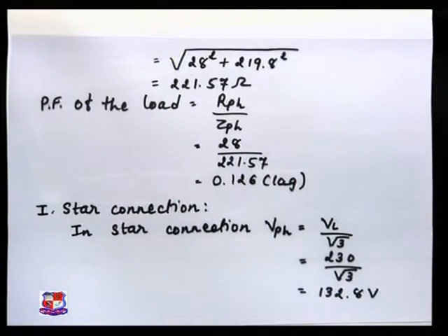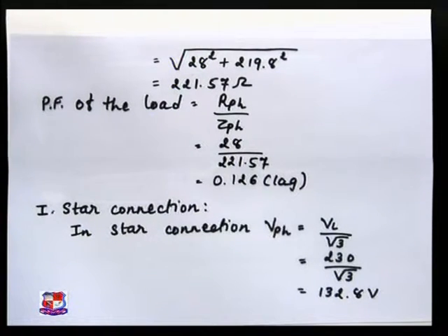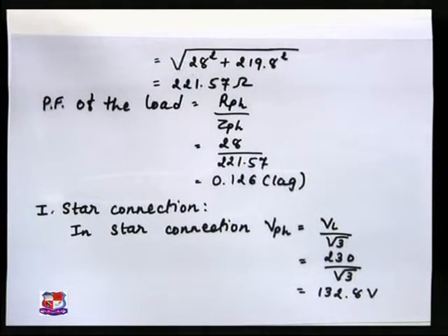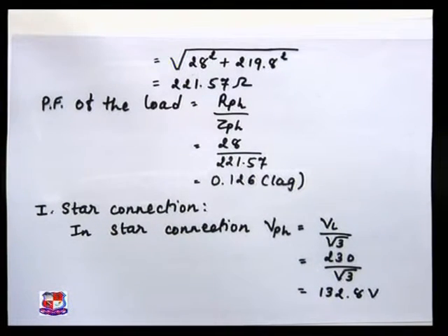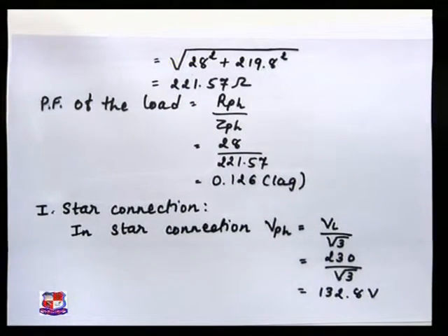Now the power factor of the load is R phase divided by Z phase. So put the values of resistance and impedance. So your power factor is 0.126 lagging. It indicates it is an inductive circuit.